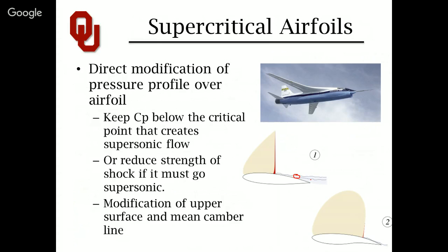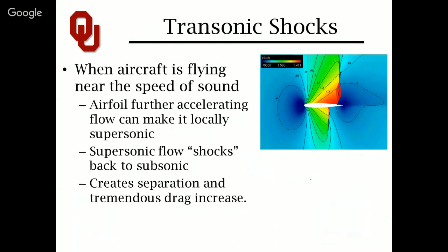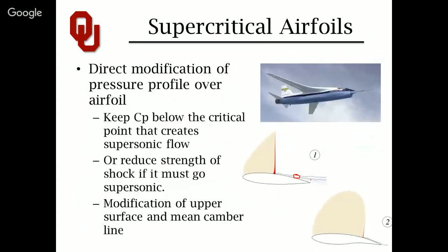But over the course of doubling the horsepower of the airplane, they went 20 knots faster. They added 20 knots to the total maximum speed of the airplane because this creates so much drag. They kept pushing and pushing harder against these transonic shocks, and honestly, the shocks were winning, just pouring fuel into the engines with little effect on the maximum speed.